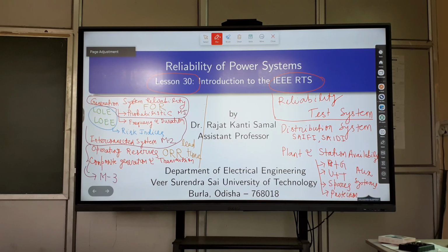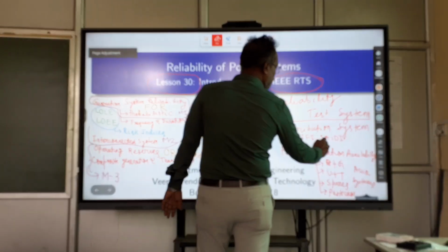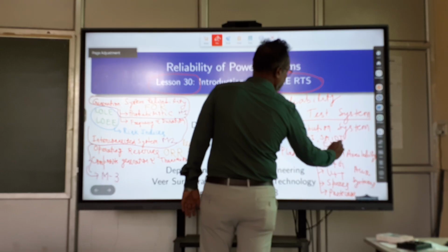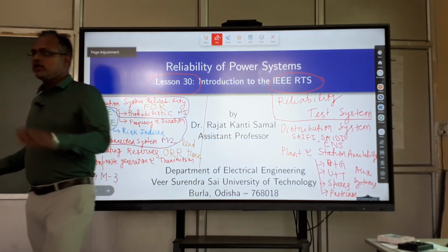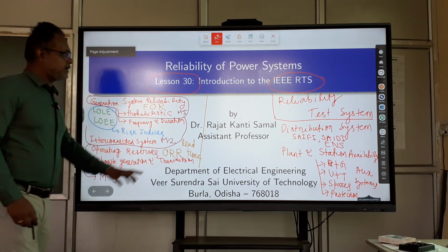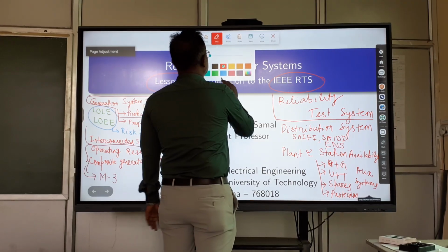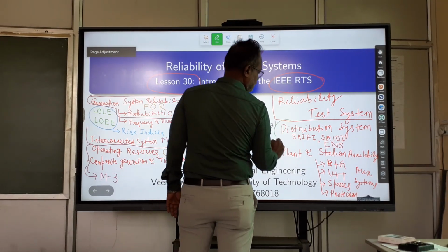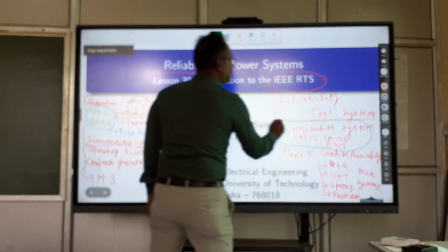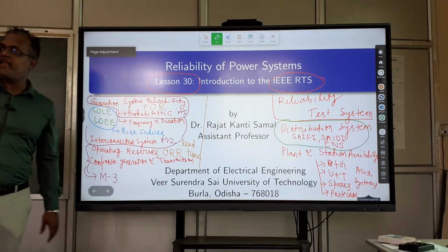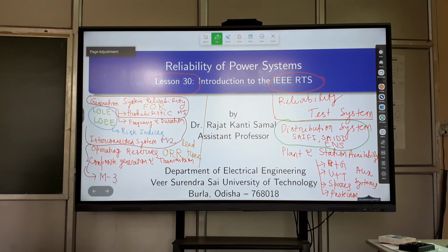So in model 4 we discussed distribution system reliability, which includes SAIDI, etc. Load oriented, customer oriented indices and some load oriented indices like ENS, energy not supplied. Okay. Now this distribution system reliability, this part, it is very important for evaluating the effectiveness of a particular measure.